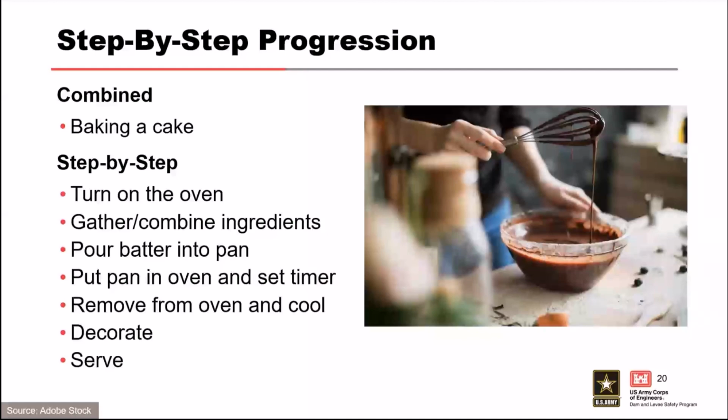You don't go to the same level of detail writing the potential failure mode description and formulating an event tree for excluded failure modes, but you do need to go through the process so that you can fully understand the failure mechanism and then fully be able to describe and justify why it was excluded.